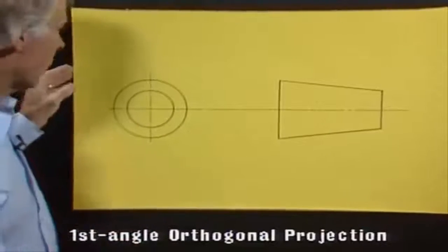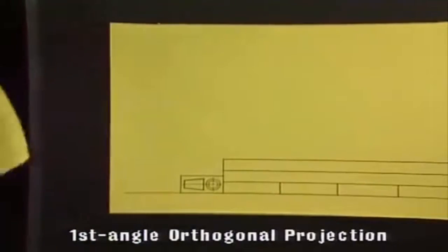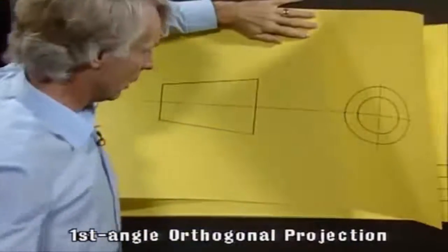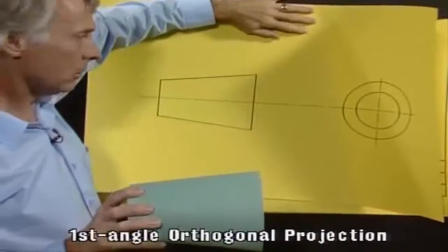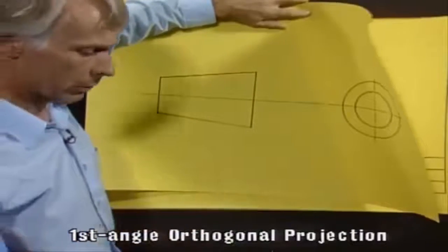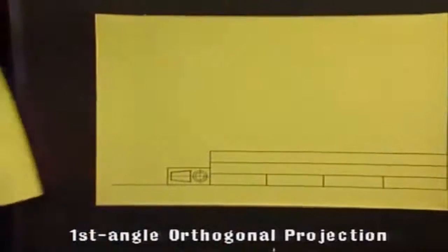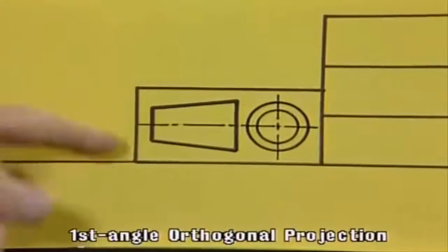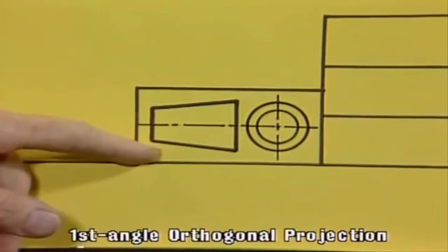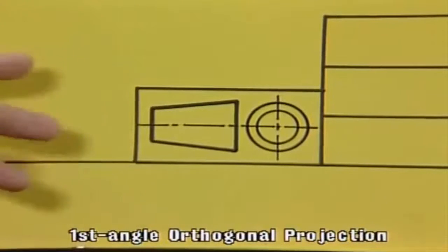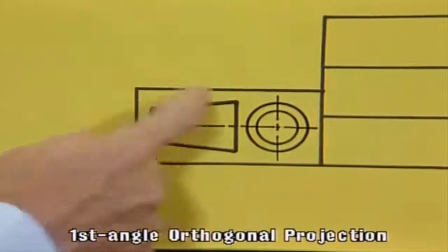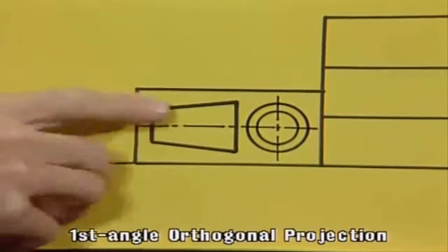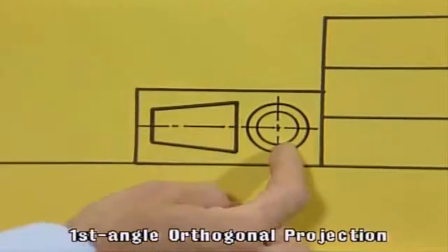And it is the same if we show the symbol the opposite way up. If we had drawn the truncated cone originally in that position, then the two concentric circles would then be over on the right hand side. And we've got that shown here in this symbol, in this corner of the title block. So again, we've got the truncated cone, front elevation. We project from the left hand side so we can see the two concentric circles, and it's shown over onto the right.